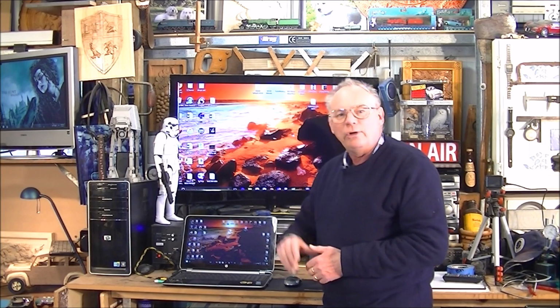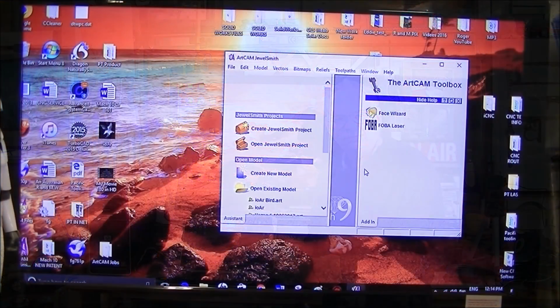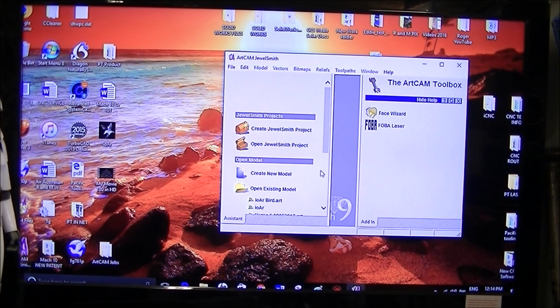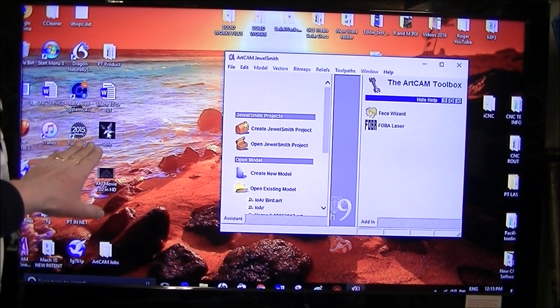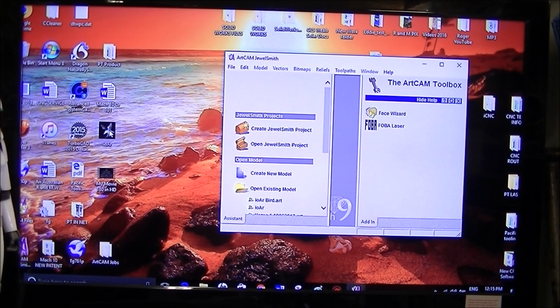Still a lot of you are asking a few questions, so I will answer those questions during this video. So having opened up the ArtCAM Jewelsmith, keep it as a small screen, and then all you really need to do is just bring your cursor onto the picture or grayscale picture or whatever you want, and left click your mouse, hold it down and drag it into ArtCAM, into this grey area here, and then release it.